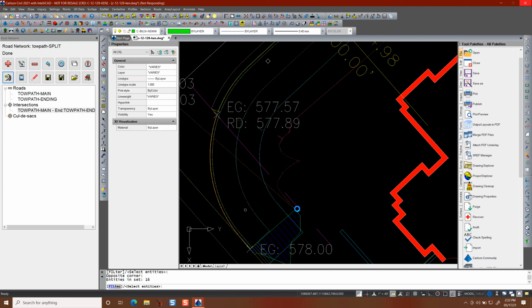So it did that part okay, except the problem is when you start a road model, a road alignment, it's defined that little 12-foot lane or 8.5-foot lane, whatever it is. And so it's expecting that outermost catch points to be perpendicular to the center line. But the problem is at this point it's not. If you can imagine that this is just a straight piece of road that goes on up this way and it goes out there, that's correct. That's the way you should do it.